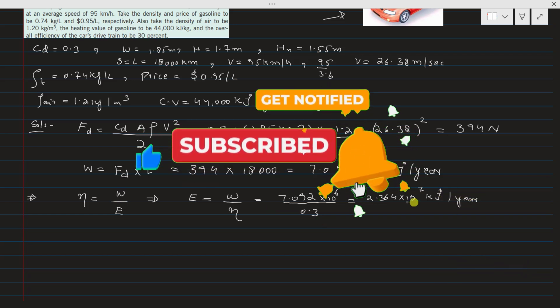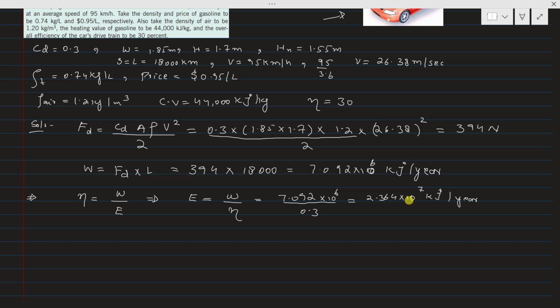2.364 multiplied by 10 to the power 7 kilojoule per year. So this much energy input is required for these vehicles when its frontal area is equal to 1.85 multiplied by 1.7 meters, when its height is not reduced. Next is to find the mass flow rate of fuel that is consumed per year. So we can say that energy input to the car is equal to mass flow rate of the fuel multiplied by calorific value of the fuel. So we are interested to find the mass flow rate of fuel.